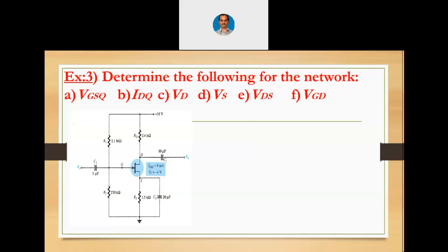Now can you quickly compute the other 2 points by using the same method? For 0.3 VP and 0.5 VP respectively, substituting IDSS by 4 and IDSS by 2. Put the answer in the chat box. 0.5 VP corresponds to IDSS by 4 and 0.3 VP corresponds to IDSS by 2.